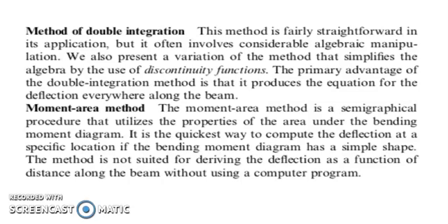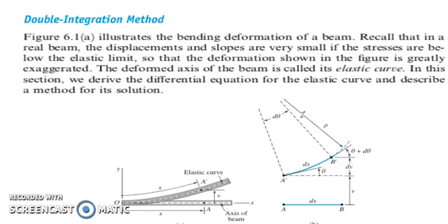The method is not suited for deriving the deflection as a function of distance along the beam without using a computer program. So the first method is the double integration method. Here we have an illustration of our figure for the double integration method, with figure A and figure B. Figure A illustrates the bending deformation of the beam.